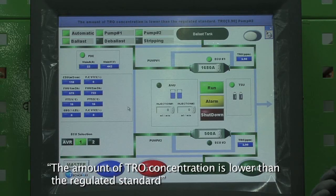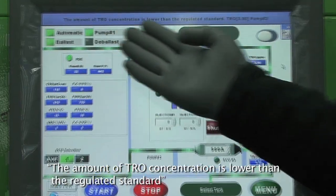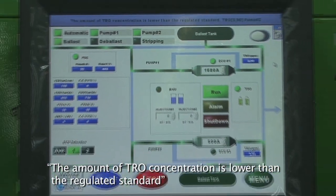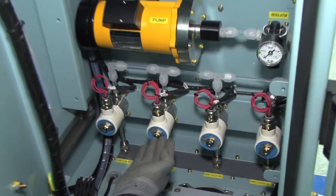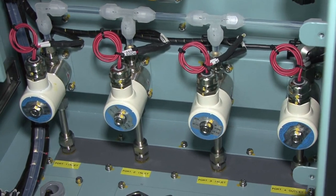Problem: ECS shuts down 10 minutes after the alarm message "The amount of TRO concentration is lower than the regulated standard" appears. Solution: Open the door of TSU and check that sampling water has flowed into the TRO sensor.